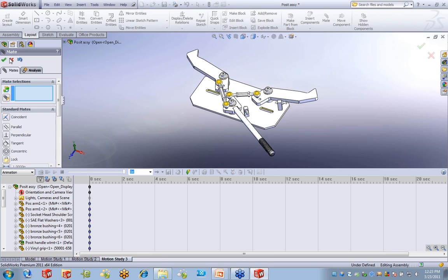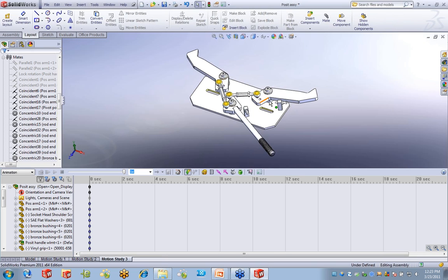It converts them into a useful tool for SolidWorks Motion. From these mates, we can drive geometry other than using a motor. We can use it to look at results at a particular joint where they're connected together. So mates play a little bit different role as we go into motion analysis.